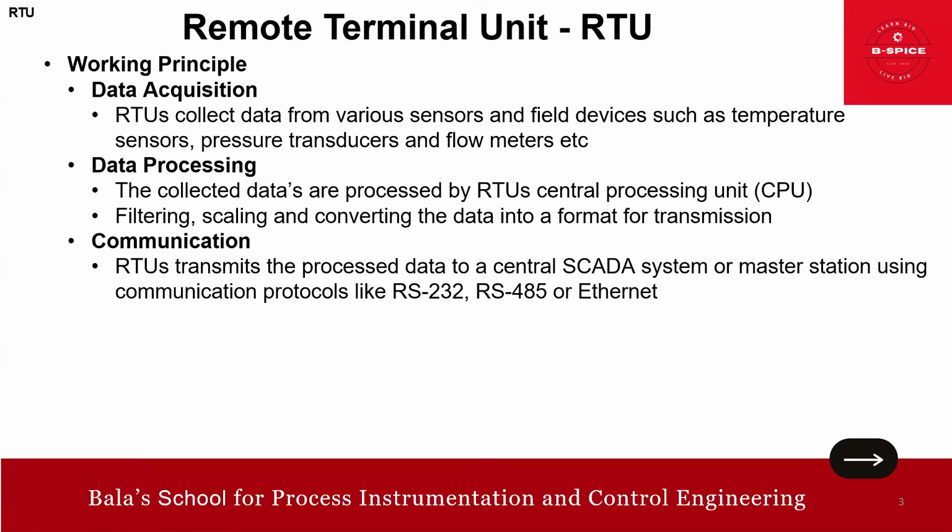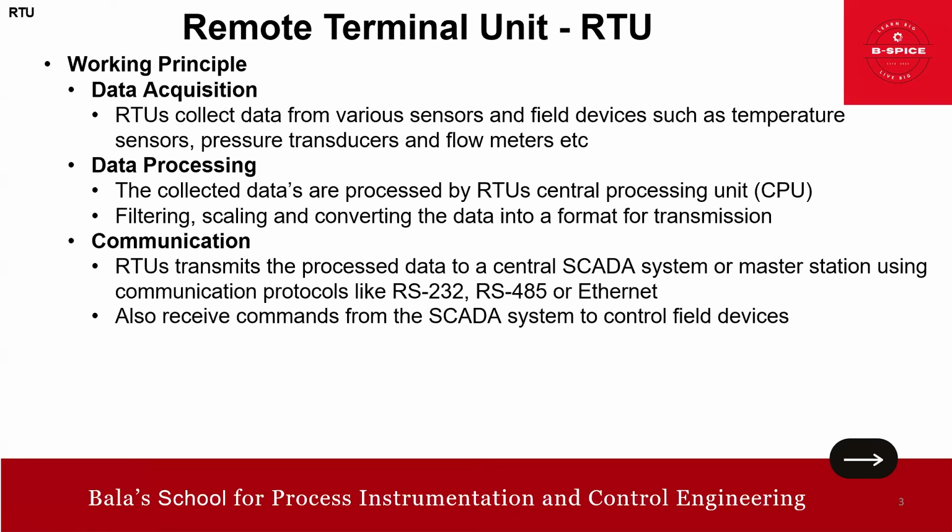Then comes the communication. RTU transmits the processed data to a central SCADA system or master station using communication protocols like RS-232, RS-485, or Ethernet, TCP/IP, and many more. I'm going to talk about that in detail in the subsequent slides. Also, it receives commands from the SCADA system to control the field devices.